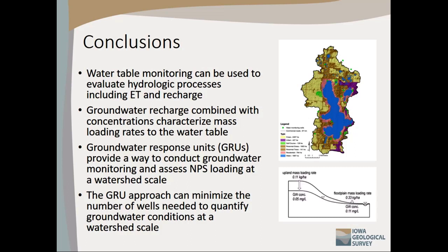Well, legal is a whole different ballgame. I'm not touching legal, but I would call groundwater where all the soil pores are at 100% saturation. Anything less than that, we're talking about water held in tension in the soil profile. In our farmed wetland study, we could see cases where the groundwater level might be 3 or 4 feet down, and we had ponded water above.